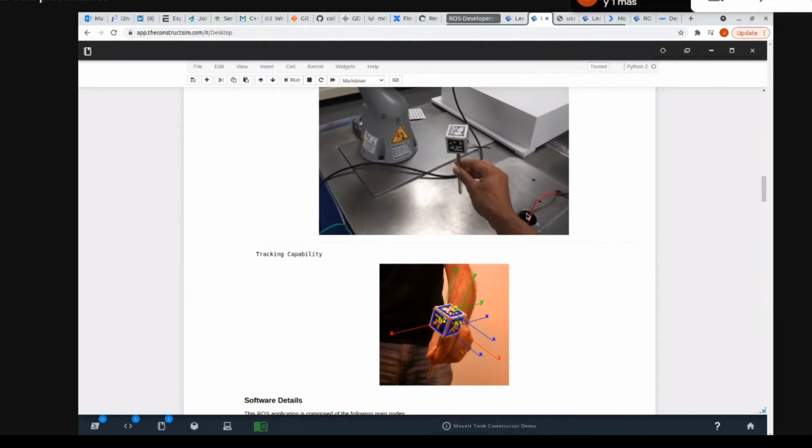The camera was taking images, and those images were being published to a ROS node that was tracking the location of the AR tags. By resolving where each tag was placed, it would then tell you the location of the wand. We would use that location to then send motion commands to the robot.